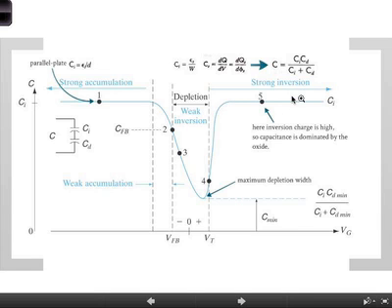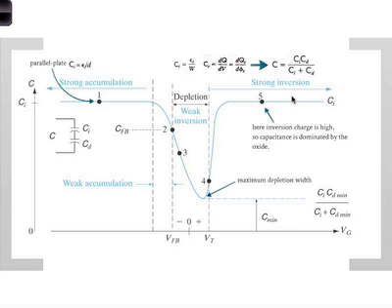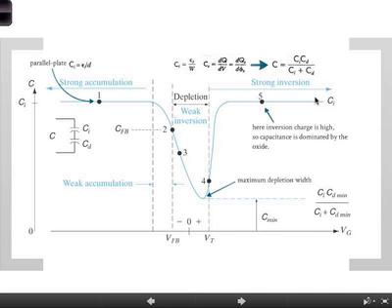After some time, the depletion region really doesn't increase anymore like we just talked about. It reaches the maximum depletion, so nothing more happens to it. So the contribution to this term is very small from the depletion, and the only contribution comes from the channel of electrons, which are majority carriers, and they can respond so fast that it becomes negligible again. Okay, so it reaches CI again up here. So that's the physics of what's happening.